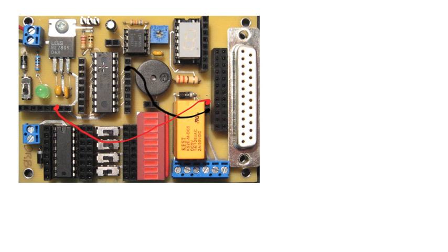The microcontroller can sink more than it can source. And so whenever we turn the port low, that makes the connection internally to ground. So we'll then have a complete path. We'll have our positive 5 volts. It'll go through our coil, out the other end of the coil, into that port, making the connection to ground. So this will serve to turn this relay on and off.